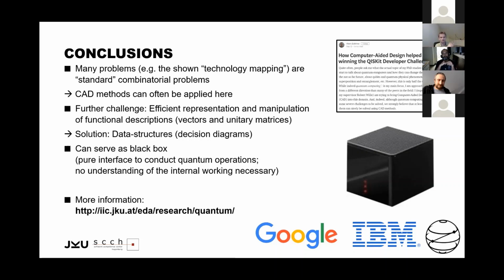And we are not only talking about the decomposition of matrices. I also talked about these edge weights, and here you have different normalization strategies. So the way you factor out values from your submatrix is also going to have an impact. The variable order, of course, is going to have an impact. So there are lots of parameters we can still tune, which eventually might yield a smaller realization.